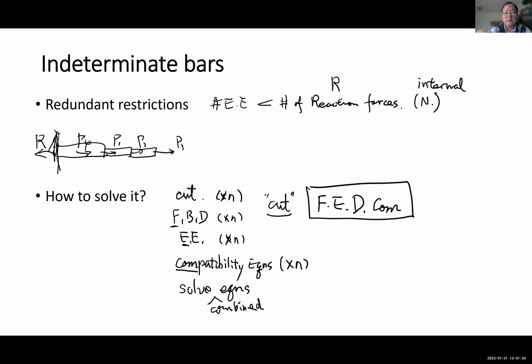Now let's say what we just showed there, right? So if you have say a bridge, okay, so if you have a load applying here, or you may have two loads there or three loads there, okay. Now how many reactions do you have? You have RA, RB, right? So two unknowns. So is this determinate or indeterminate? It's determinate. Because how many equations can you write?